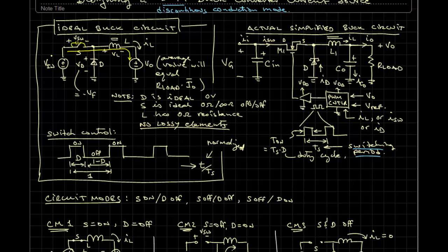And it will rise very quickly, and it will rise up to a voltage of Vin. And you might say, well, why does it go all the way to Vin? Well, the assumption is there's enough energy in the inductor that it would take a tremendous amount of voltage across that tiny little capacitance of the switch to store all that energy that was initially in the inductor. So the switch voltage will rise to Vin, at which point the voltage across Vd will be 0. Note that V switch plus Vd is always equal to Vin. Okay, so as the switch voltage rises, the diode voltage goes down.